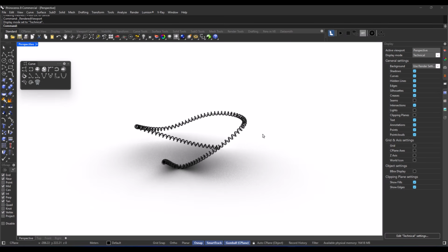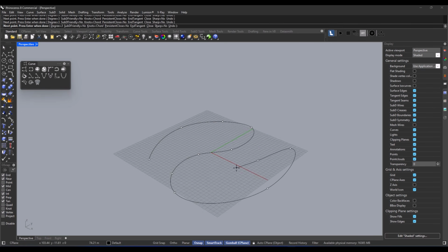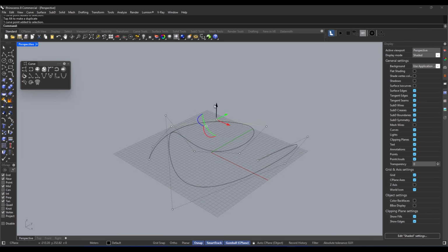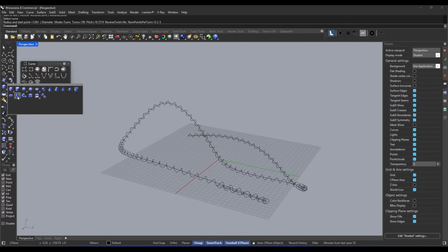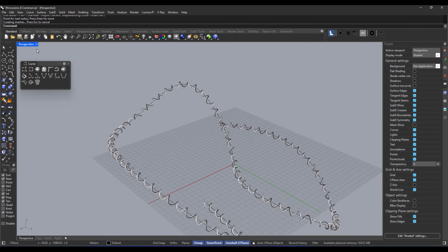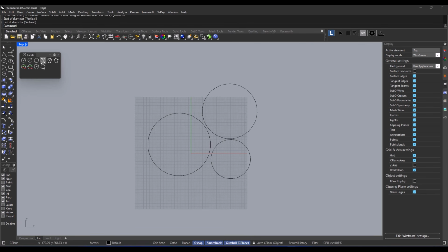All right, so in this episode, we got to know a bunch of basic Rhino commands, from drawing points and lines to creating curves, circles, ellipses, arcs, and polygons. Then we learned how to use the transform commands to move, rotate, scale, and repeat objects. And finally, we got into the editing tools like trim, split, and join. Honestly, this part is the backbone of precise modeling in Rhino. I seriously recommend you try out all the different commands in each cascade so that over time, the logic of working with these tools becomes second nature to you.